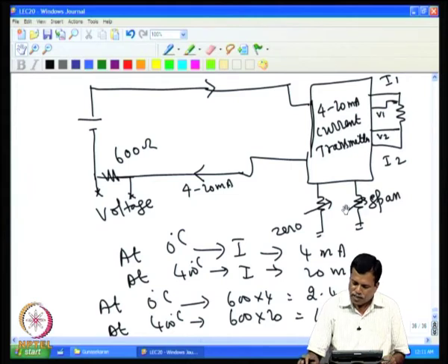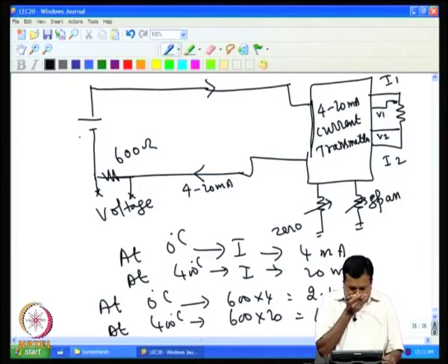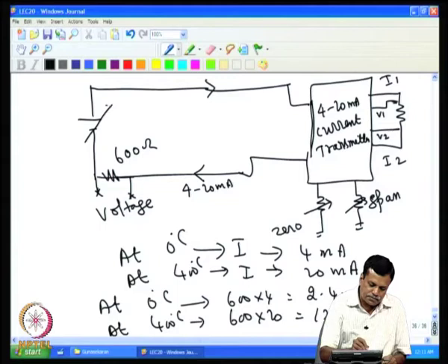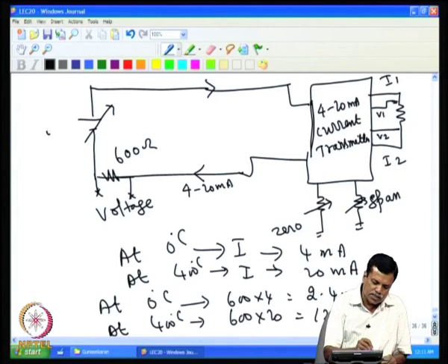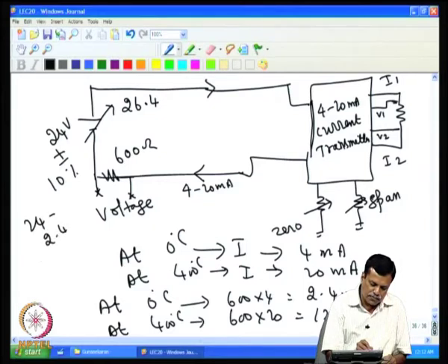So, this is the system that we have to design now. We start our story from the supply. If we take the supply here, this supply voltage is normally given as 24 volt supply, but it invariably varies plus or minus 10%. That means it may go to 26.4 on the higher side and on the lower side 2.4 volt down, that is 24 minus 2.4, that comes to 21.6.